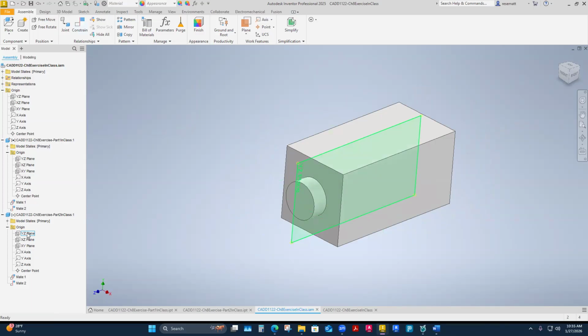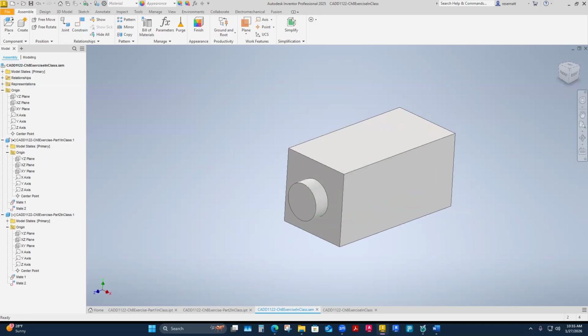If that pin needed to rotate, I would have to free up that constraint. So if I did need that pin to turn and rotate, this is not going to allow that. That plane to plane alignment is going to keep it. But let's just say this is an inserted, interference fit anyway. It's size on size. So once I insert this, I'm not planning on it rotating. I'm just trying to seat it in there. And this is how I want it to be.